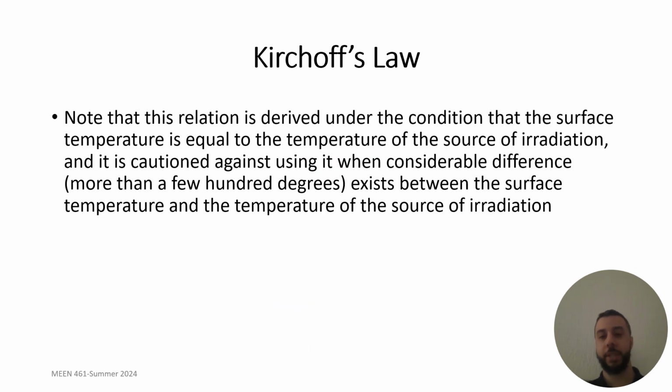We do have a condition to use Kirchhoff's law. Note that this relation is derived under the condition that the surface temperature is equal to the temperature of the source of irradiation, and it is cautioned against using it when a considerable difference, more than a few hundred degrees, exists between the surface temperature and the temperature of the source of irradiation.